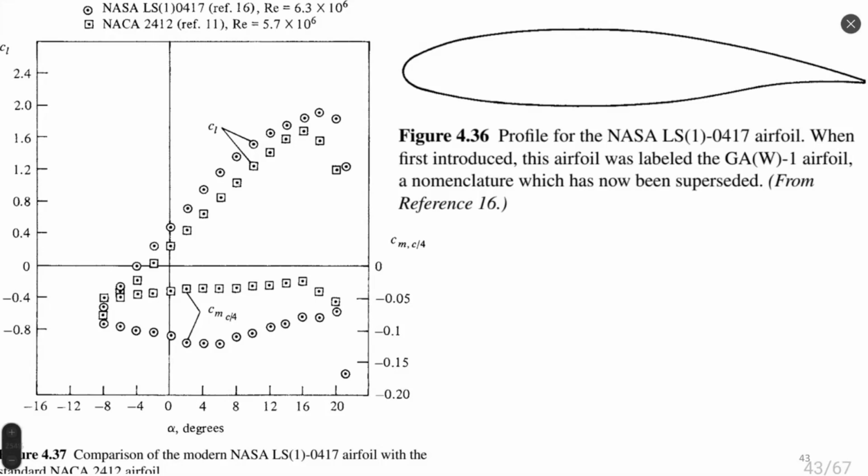It's not possible for all airfoils. It's just one example. For some airfoils, this optimization is still possible. For other airfoils, not. Modern airfoils are on the limit of optimal operation. If you take any commercial airfoil of the last generation, you will see that it's not possible to optimize anymore because all ways to optimize it were already used. All geometrical possibilities were simulated. But for older airfoils, it's still possible to provide such optimization.